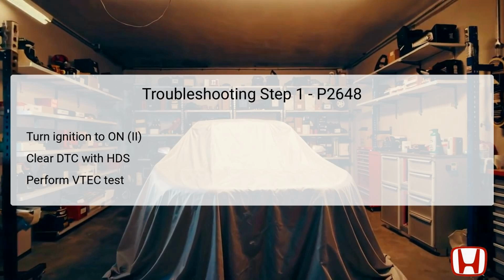Clearing the code is crucial as it allows the technician to refresh the monitoring parameters of the vehicle's systems. Following this, the VTEC test from the inspection menu in the HDS must be performed. This test assesses the operational capacity of the VTEC system and helps verify whether the issue is intermittent or consistent. If the results from this step are satisfactory, further diagnostics may reveal underlying connection issues or component failure.